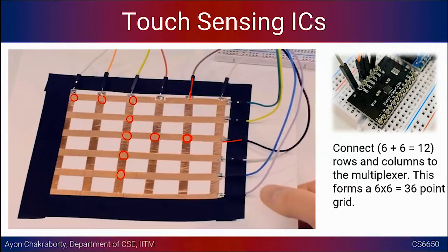Okay, so you will read the sensing values from all of these 12 pins continuously, and from those 12 values you have to figure out which particular portion in this grid was touched, right. So instead of having a 36 channel capacitance sensor, we are doing it with a 12 channel one, where we can do this crisscross of these electrodes or strips, and based on the values that you are receiving on the microcontroller end, you can figure out an algorithm to detect a particular touch point.